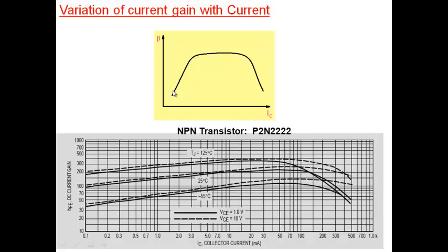Okay, so, for example, this is important because you may take your transistor and you may read that beta is supposed to be 100, make an amplifier, and you're driving too much current into your transistor. If you're driving too much current, you may exceed this particular threshold and your beta may actually be 10 or 20 or 30. It may be smaller. Similarly, you may be driving very low current into your transistor and your beta may be smaller.